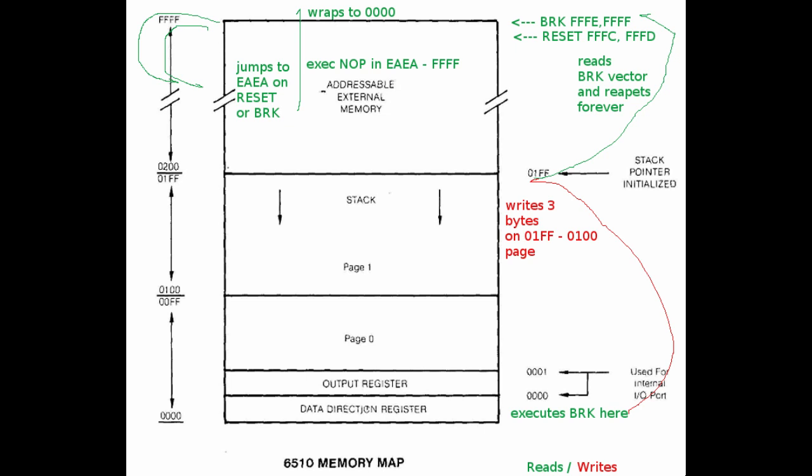So with enough cycles, it will scan all the page 1 memory area. But then after these 3 writes, it will read the locations FFFE and FFFF, and again it will read EA, and will jump again as it did at the reset moment, and the cycle repeats forever.